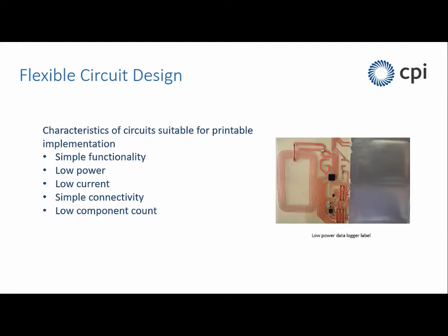However, we don't have large arrays, we don't have large connectivity available to us. We have 1 or 2 layers or 3 layers of conductors. We don't have 6-layer PCBs or 20-layer PCBs available. So you have to constrain your requirements in that respect. Low power and low current are also both requirements, or desirable anyway. It may be that you have an application where you only want your device to last 10 minutes. We do have one at the moment, which is temperature monitoring in a process where a device will only need to last 10 minutes, and then we'll have to be able to read the data out at the end. But it doesn't have a long lifetime requirement.